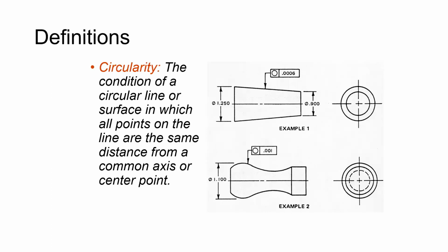Wood lathes. But the circularity, when you set up your part, you try to get your stock in your lathe running straight. So machinists have always got a dial indicator and a magnetic base, and they'll put that dial indicator on their part when they put their stock in the chuck, and they'll rotate that stock or that chuck until that dial indicator is not moving anywhere. So they're trying to get that running as true and straight before they make their part, so that their part comes out right. So they're measuring circularity where that dial indicator is touching, and that sets that part up to run correctly.